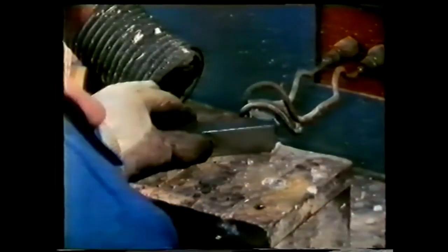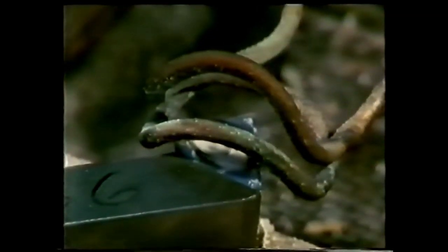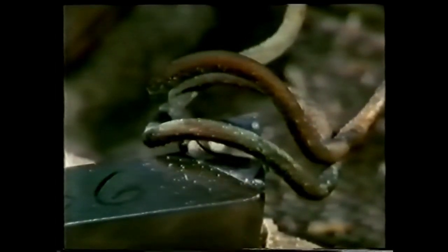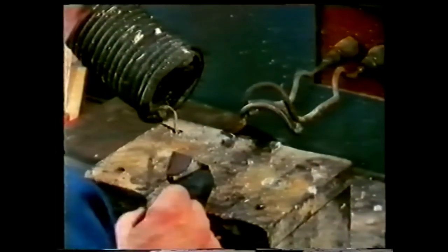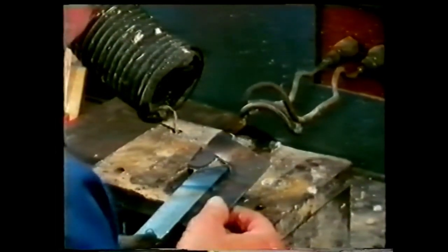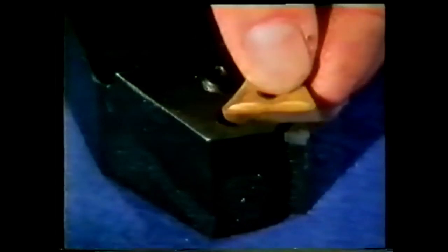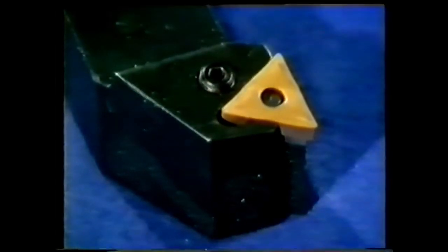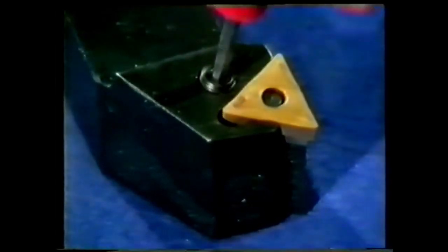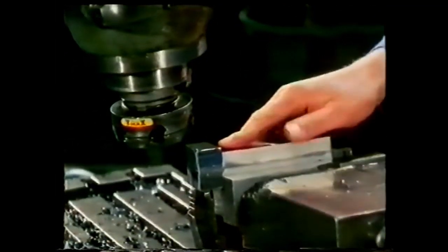In the beginning, because of the expense of the process, the cemented carbide tips were brazed onto the tool body. This only added to the cost, because when the tip wore down, it had to be reground painstakingly using a silicon carbide wheel. And after all that, the tool had to be reset. Nowadays, to save time and money, specially prepared inserts and holders are used. The holders are made from toughened steel, which first undergoes a series of milling operations.